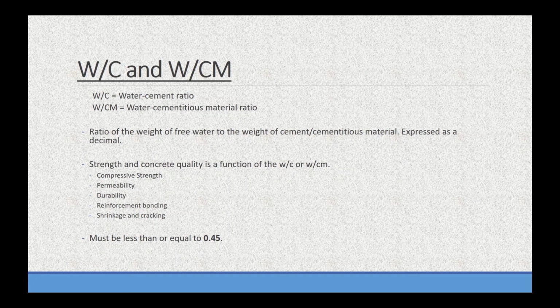So for Spec 4, it needs to be 0.45, and that's 0.45 basically through placement, so that it needs to be 0.45 even when it's on site. So keep in mind, if you're adding water on site or anything like that, that plays into that 0.45.